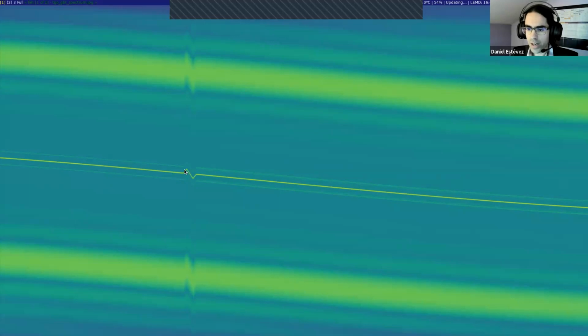So here we are actually seeing the frequency that originated on Earth being received by the spacecraft, replicated, and multiplied in frequency, because the uplink is 7-point-something gigahertz. So it's multiplied in frequency to generate this 8.4 gigahertz and sent back to Earth. And this is the sweep. This is the frequency sweep they do with the telecommand when they start transmitting.